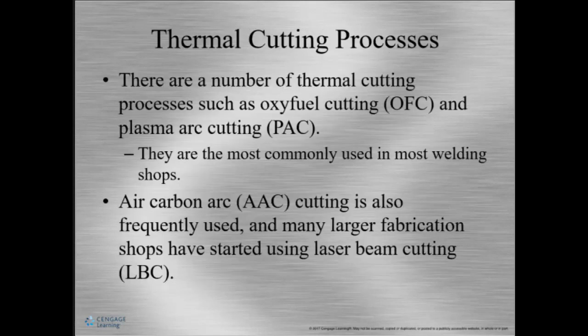All right, so let's talk a little bit about cutting processes, or thermal cutting processes, thermal meaning heat. Oxyfuel cutting and PAC, or plasma arc cutting, are the most common thermal cutting processes you'll come across. There's also air carbon arc and even laser beam cutting.